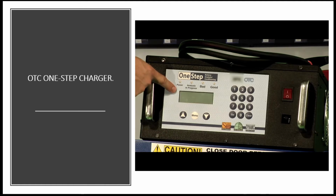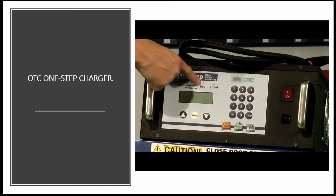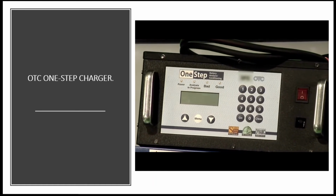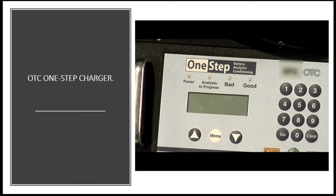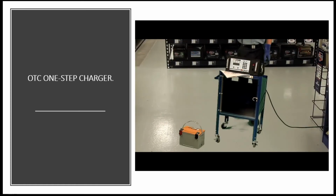Menus and input screens are shown on the display. The status lights indicate that the battery charger and analyzer is powered on, a test is in progress, a fault is found, and the battery is bad. Or the testing procedure is complete and the battery is good. The bad light is red and the good light is green. Connect the battery clamp test leads to the battery post to apply voltage measurement and charge load.